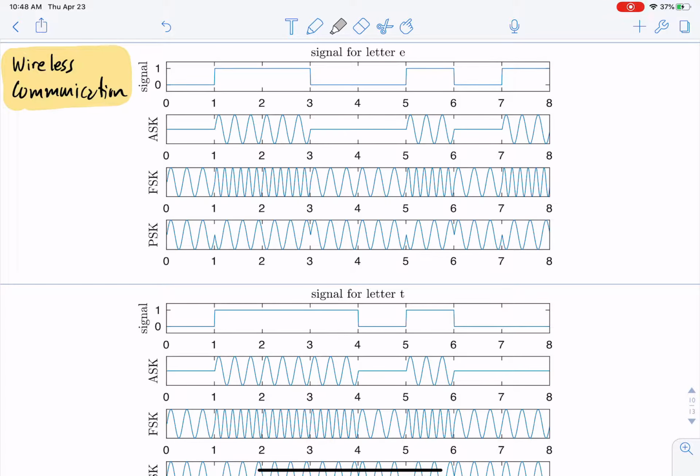So this is a little less obvious, but it's like, where in the cycle are you? So you can see this one, you're starting and you're about to go up, and then you go down. Whereas in this one, you're starting at the 0 and then you go down first. Okay, so it's a different phase. You could also start at the top and go down. So there's different kinds of phase shift keys, but this is a very simple one where it's just up or down at the beginning. So again, you can see, start here, it's up, down, down, up, up, down, up, down.